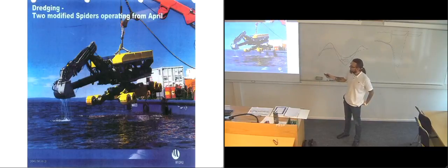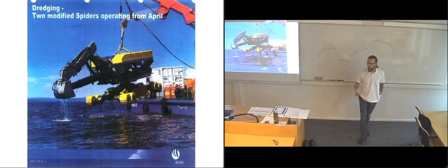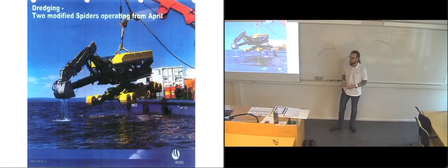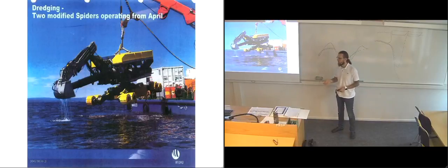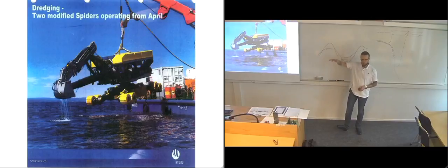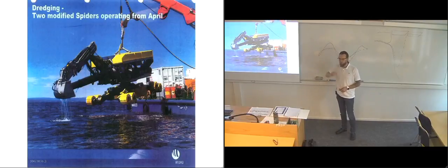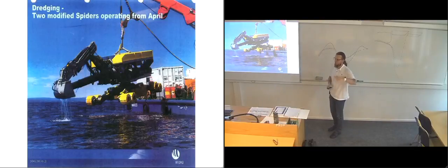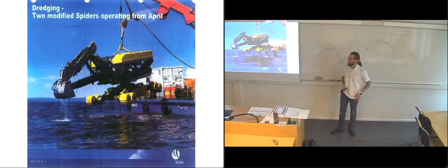Like this one, it does have buoyancy elements on top here. Those yellow ones we can see on the top. They are buoyancy elements to make it lighter in water, but it still has a negative buoyancy, so it won't float. Like an ROV might sometimes be adjusted with buoyancy so that if you cut all the power to the thrusters, it's going to slowly just rise to the surface because it's floating. While this one, it will sink if you release it. But it won't slam down like a rock. It doesn't have all that much weight.